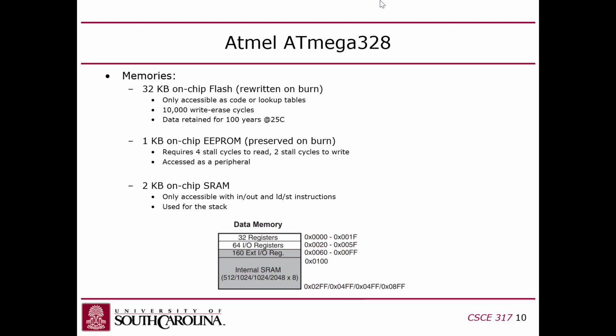All right, those don't map to memory. They map to these registers that allow you to control or monitor hardware. Generally speaking, in this case, they are either pins that allow you to go off chip, or they are internal peripherals, which are circuits that are on the chip, but they're separate from the main data path of the processor.